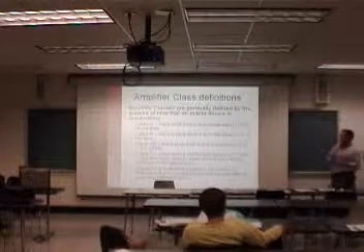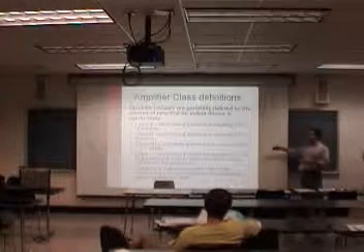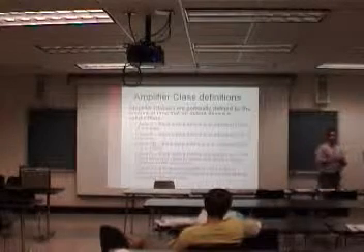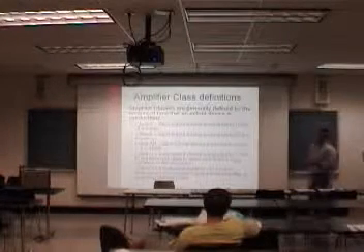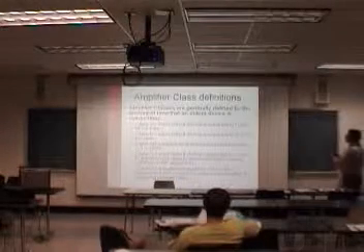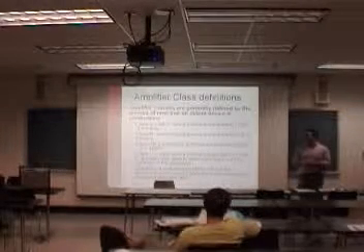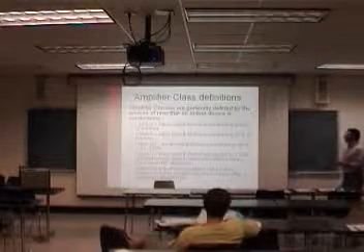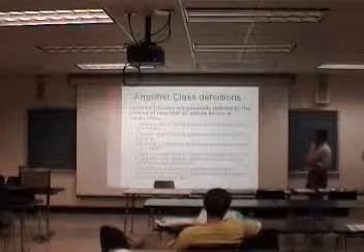So it's one of these things that, strictly speaking, is not Class A, because it's not 100%. But it's also not like most Class AB amps, which are just a little over 50%. So it's clearly more towards Class A than Class AB, but to call it strictly Class A is also not completely correct. So these are kind of the standards, and these are the amplifiers that we've seen in musical equipment from the 50s, the dawn of really amplifying electronics, up until probably the 80s or 90s.